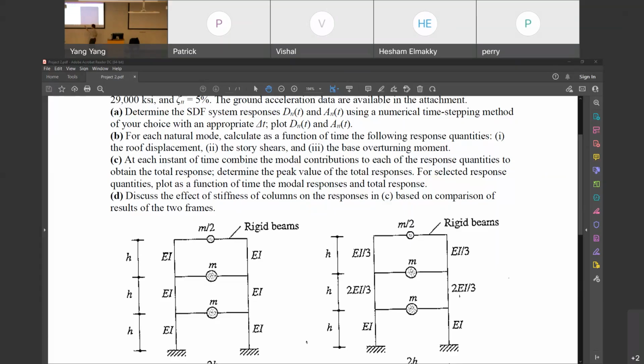So with cracking, the damping ratio is higher. Why? Because steel yields, and if there is cracking, the friction between the cracked surfaces will contribute to the damping. For wood, would you expect a higher damping or smaller? Higher, yes, nice. That's what I meant: 6 to 7% for wood.